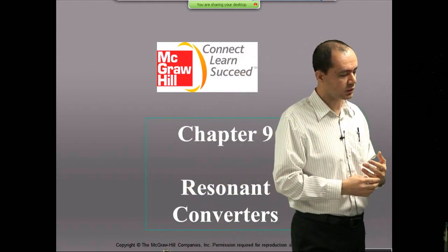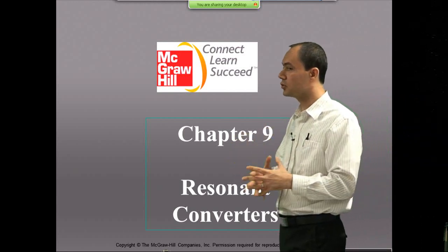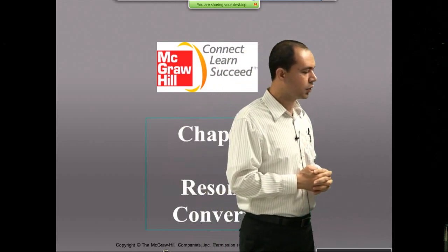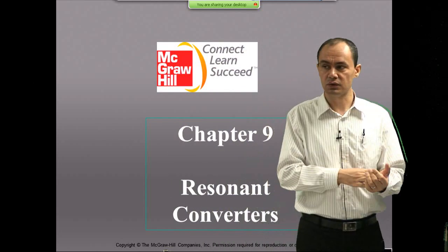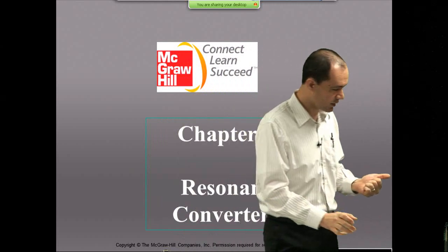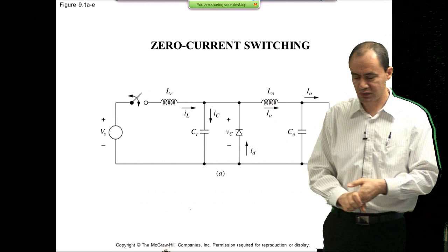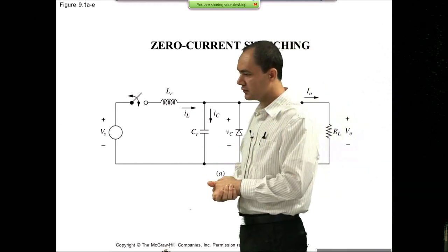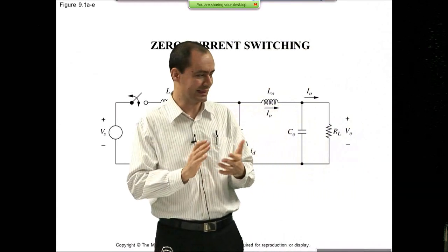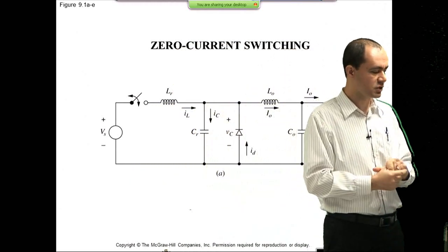The objective is either to have a sinusoidal signal. For instance, you are trying to make an inverter, and having a purely sinusoidal signal is very important to you. Or you can achieve, for instance, ZVS, zero voltage switching, or ZCS, zero current switching through this resonance. We have analyzed, and you can categorize these converters into resonant switch converters, resonant load converters, and resonant DC link converters.